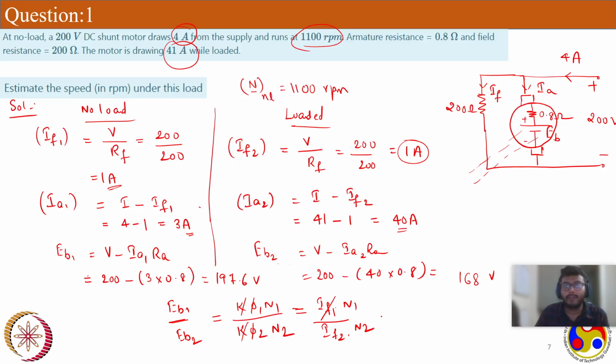These are my rotational losses at no load conditions. So at no load condition, my motor will rotate just to deliver these rotational losses. Now go back to our required equation. Now I know these rotational losses. I know Ia square, I know Ra. I just have to get the shaft power. Once I get shaft power, I will substitute here to get the shaft torque. Now please calculate shaft power along with me.